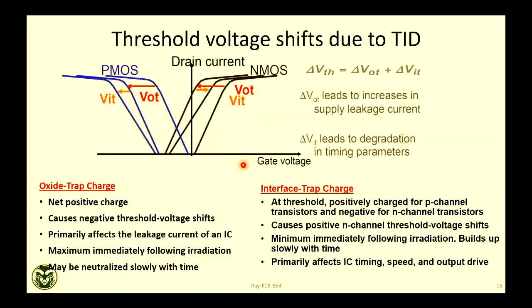Now, if you look at the threshold voltage shift, suppose you have a thick oxide, say 10 nanometer oxide, which is true for flash memory cell. Now, if you have a PMOS versus NMOS, their threshold voltage shift will be very different. For example, you typically trap holes or positive charge in the gate dielectric after radiation. So when you have positive trapped charge, the threshold voltage will shift towards negative direction, right? So VT will decrease. This red line shows the oxide trapping related threshold voltage shift. So both NMOS and PMOS threshold voltage will shift negative. But in terms of magnitude, PMOS threshold voltage magnitude will increase because PMOS threshold voltage starts with a negative value, it becomes more negative. So VT of PMOS will increase magnitude wise, VT of NMOS will decrease. So that means NMOS will become more and more leaky. So this is a leakage current. So leakage current will increase with radiation effects.